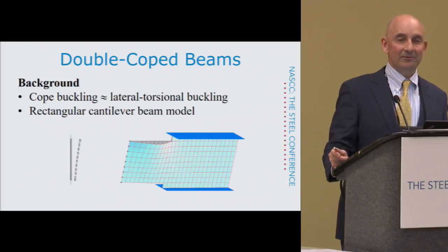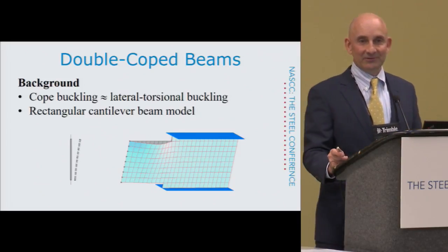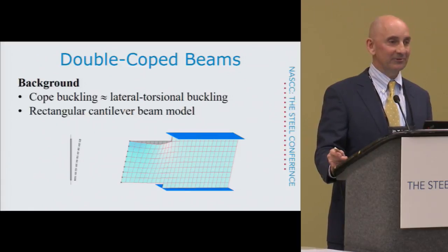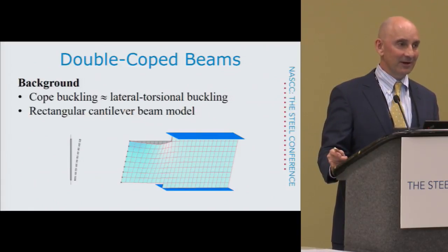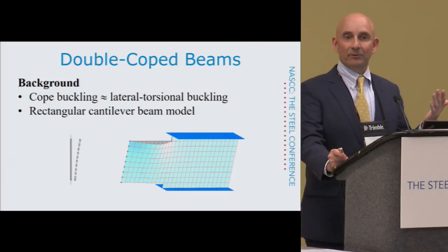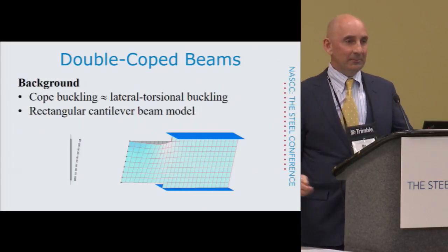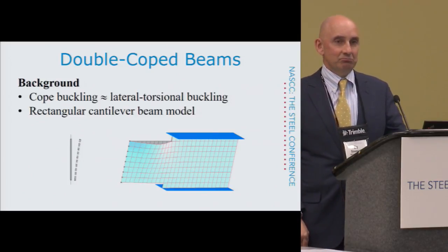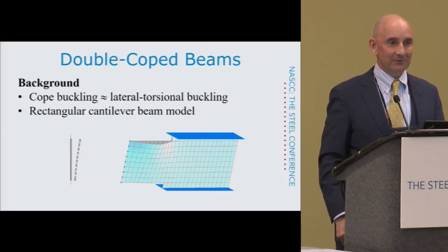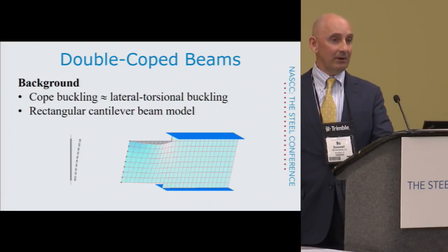It's just negligible, because in a wide flange beam the dimensions are such that the distortion is imperceptible. So you get a negligible reduction due to distortional buckling for normal lateral torsional buckling design. In this case, it might be enough that we have to apply some type of fudge factor again on top of our lateral torsional buckling model, but we have to start somewhere.